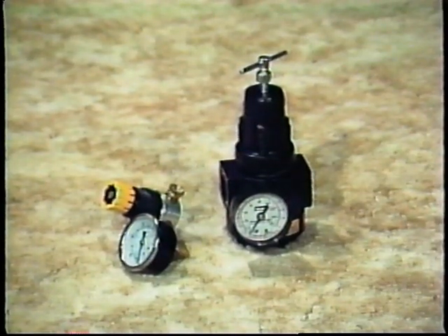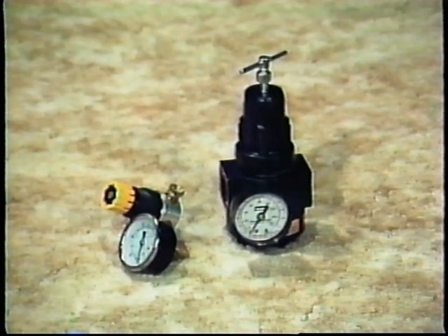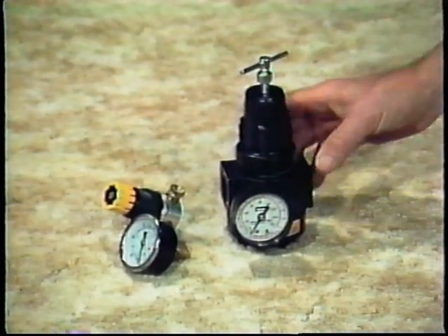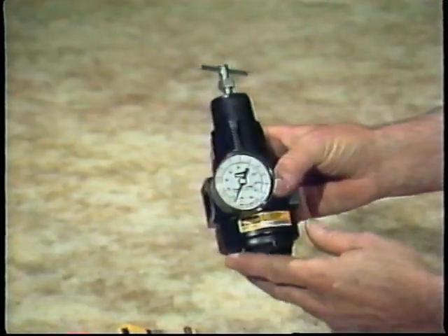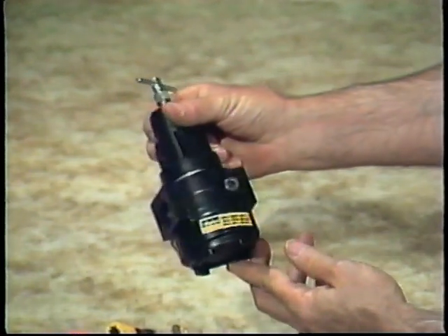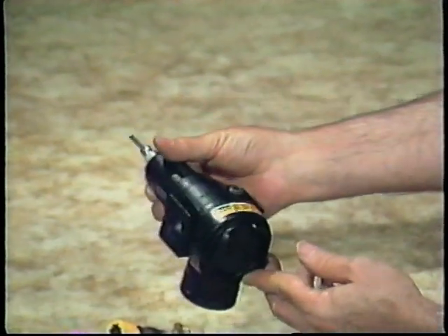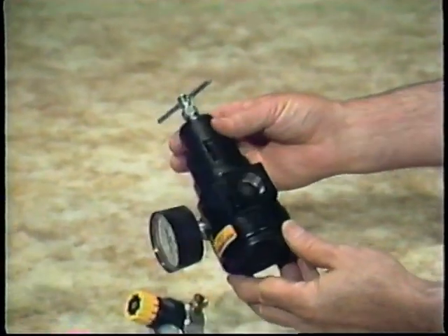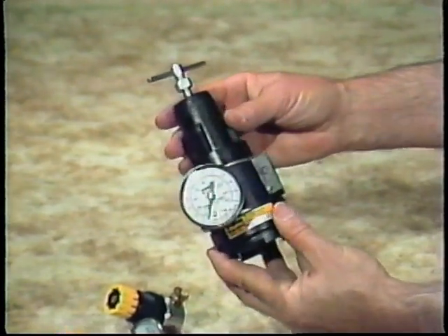The sequence valve we used in this particular circuit is a device you may remember from Lesson 4. It's called a pressure regulator. It is normally used to reduce air pressure going to an actuator or circuit down to a certain preset value, and thus save air usage. It also helps keep system air pressure constant, regardless of changes in upstream pressure.